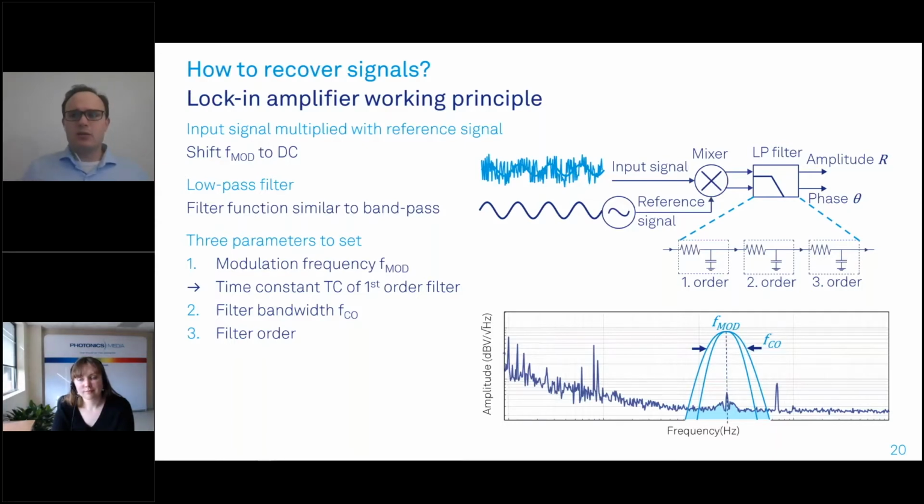And this allows you to do, for example, sometimes even more precise phase measurements, because the phase detection is more sensitive, for example, at the 10th harmonic. And interestingly, it can even help you to get more signal in your fundamental frequency, because if you remember the Fourier series of the rectangular function, the fundamental is even more than one, because the peak gets counteracted by the harmonics.